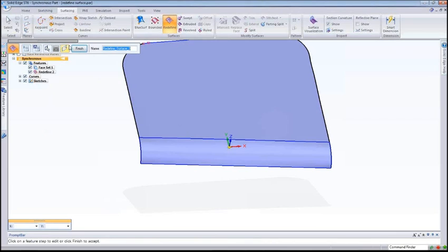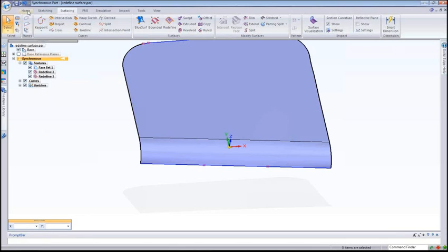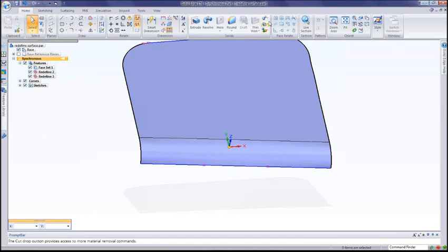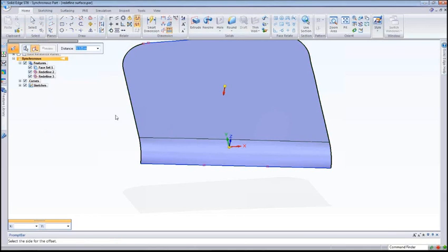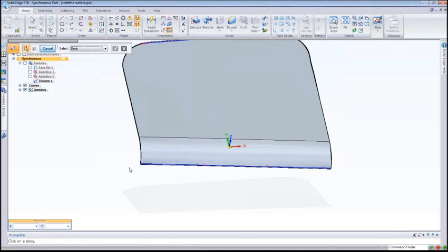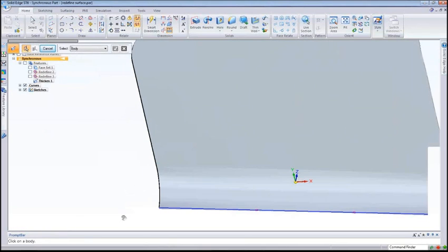Preview it out, and I'm finished. It's that easy. It's absolutely amazing. From here, you can take these brand new two surfaces that I've got, stitch them together, stitch them over to something else, and make it into a solid. Or you could even reach over here and say, you know what? Let's take that guy right there and let's do a thicken off of both surfaces. Maybe we want it to be about, what do you think, 1/4 of an inch? And now I've got a solid. Okay? That is so cool.